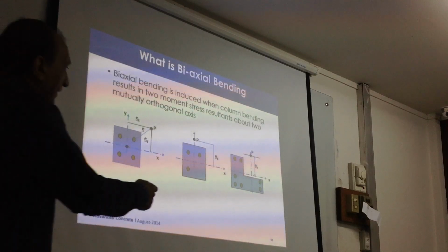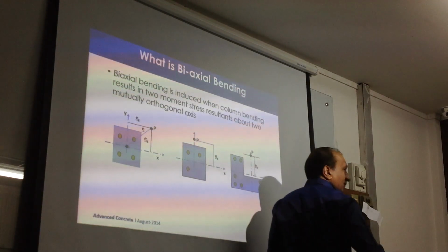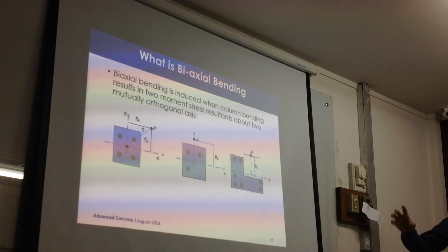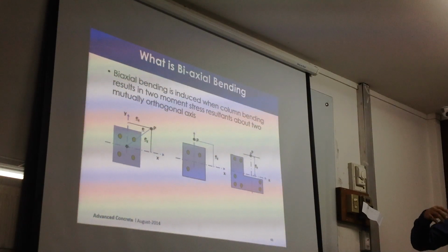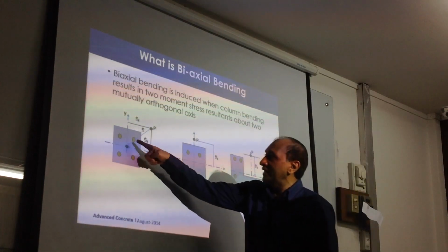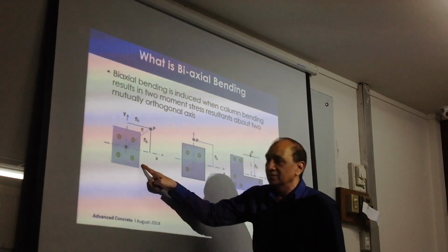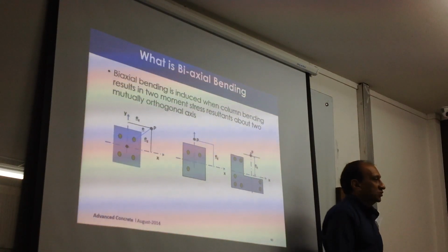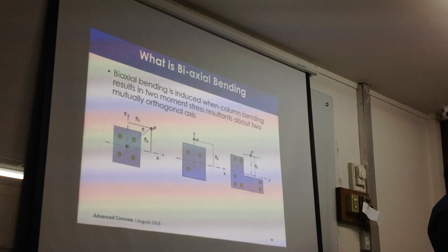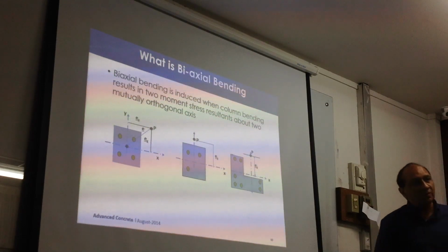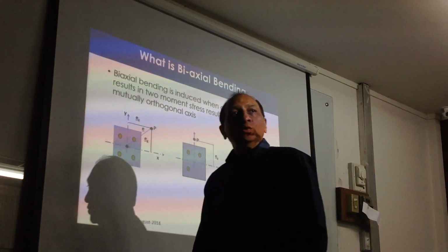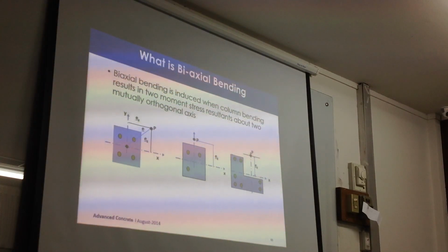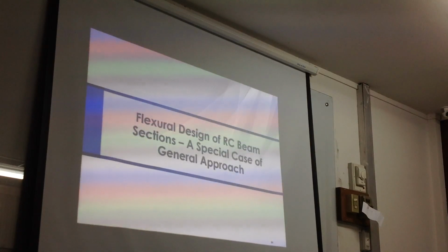And this is of course a case where you will have complicated biaxial bending because the section is unsymmetrical and also the loading is offset. So both things will combine together to cause a very complex situation, and here the bending axis will be perpendicular to this line. Here, not. Different situation altogether, right? That's why unsymmetrical sections are very hard to estimate anything about their behavior. Any assumption that we made about unsymmetrical sections fails at some point.